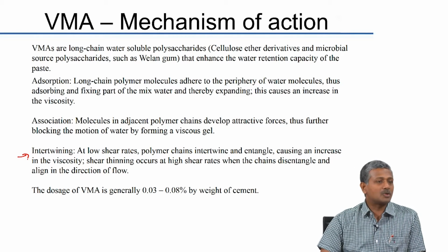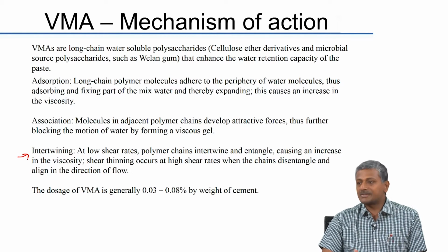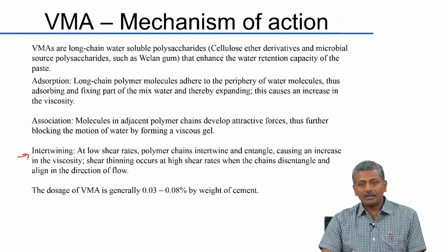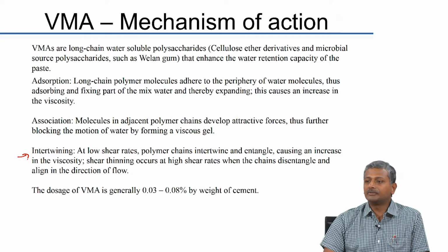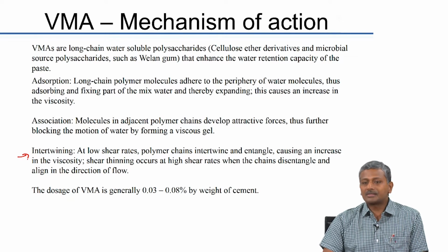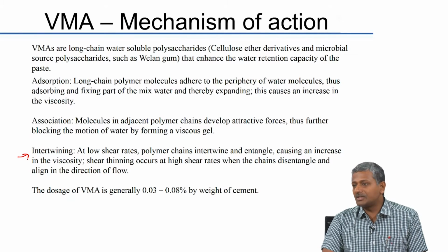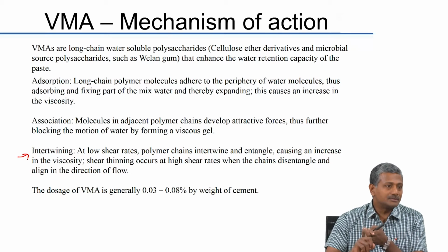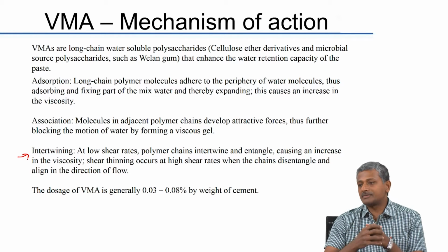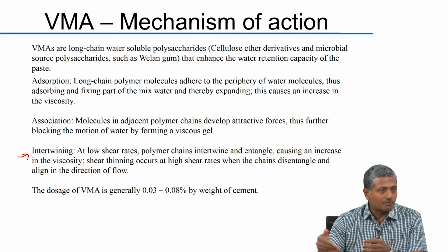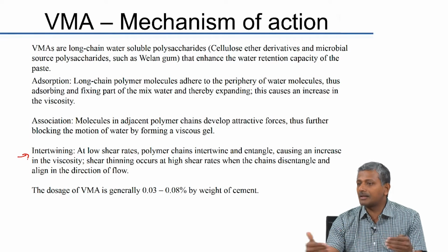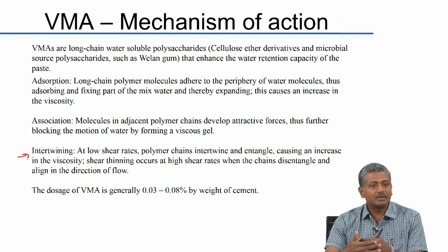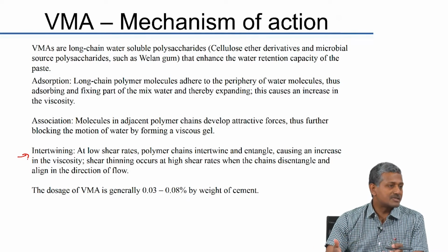When the material is at rest, the molecules of the VMA, which are long chain polymers, start intertwining or entangling with each other. When they are entangled, they have a cohesive network built in the system, but when you start vibrating this concrete or when the concrete is flowing, these entangled chains get disentangled and straighten up. When the chains straighten up, there is very little resistance to the flow.